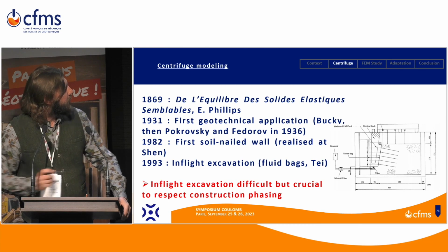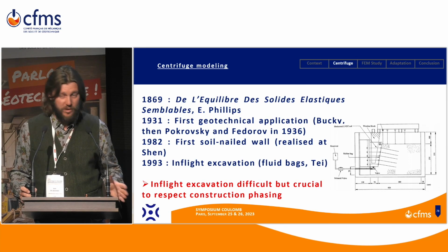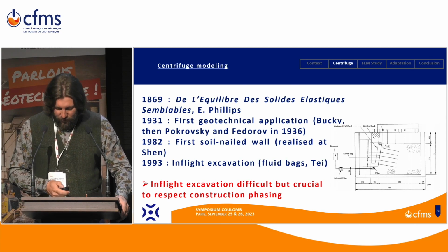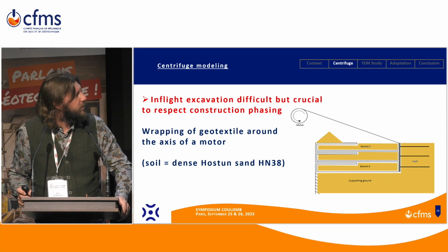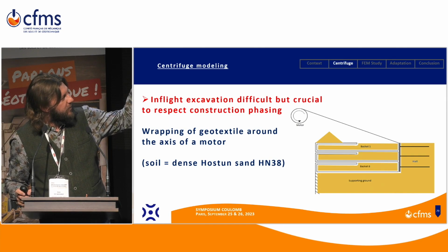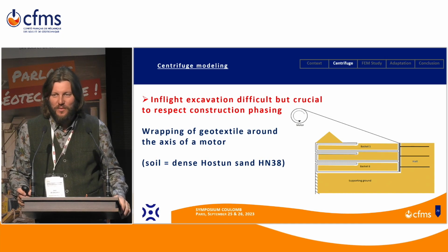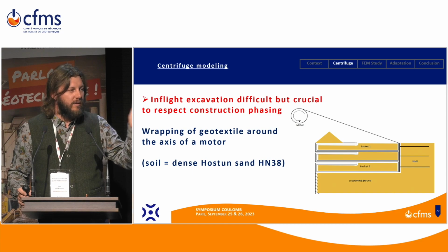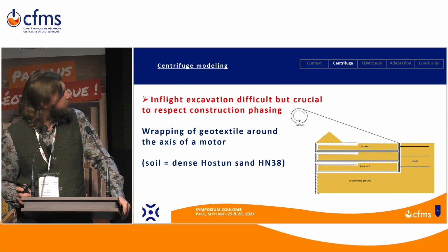So the in-flight excavation is clearly the most difficult part, but it's also crucial to respect the construction phasing and to give relevant results. So that's why we try to do it using real soil. We use a motor and a geotextile wrapped around the axis of the motor, and the geotextile makes some turns around the soil. So when you launch the motor, it wraps the geotextile around the axis, and step by step you reject baskets of soil.